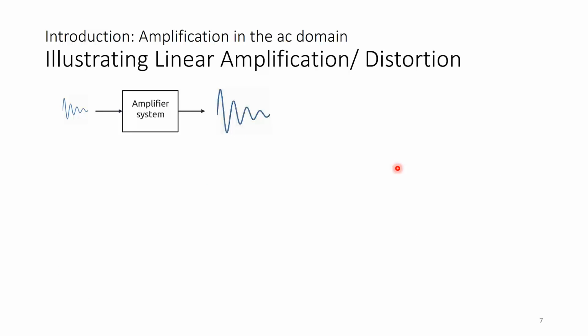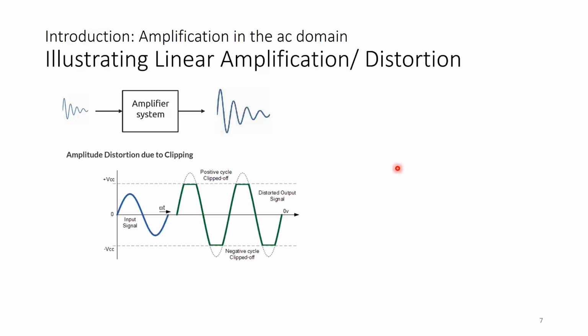Again with this amplifier system, when there is amplitude distortion, when the input amplitude becomes too large, clipping becomes substantial and forces the output waveform signal to exceed the power supply voltage rails here, causing parts of the waveform signal to become flattened or clipped off. To avoid this clipping, the maximum value of the input signal must be limited to a level that will prevent this clipping effect. There can also be other types of amplitude distortion, as well as frequency distortion and phase delay distortion.